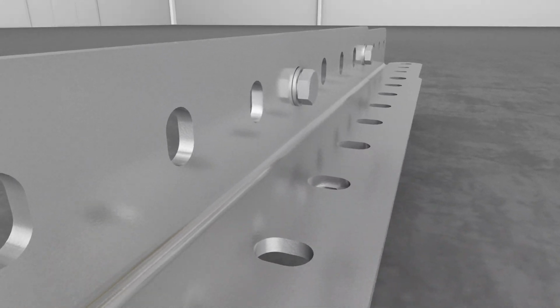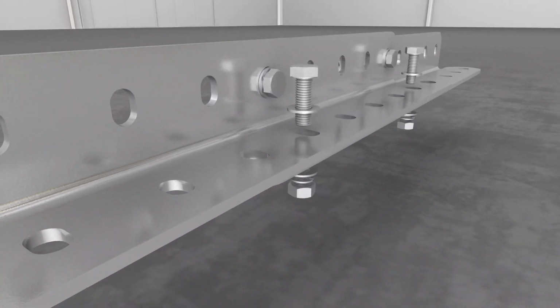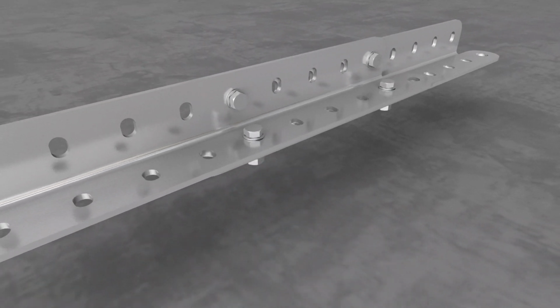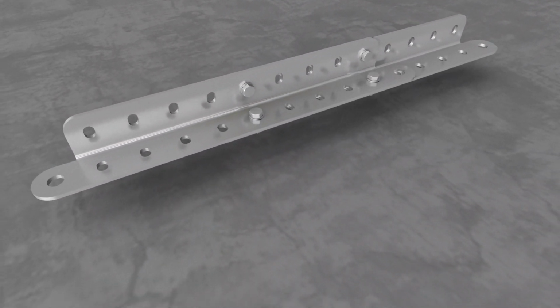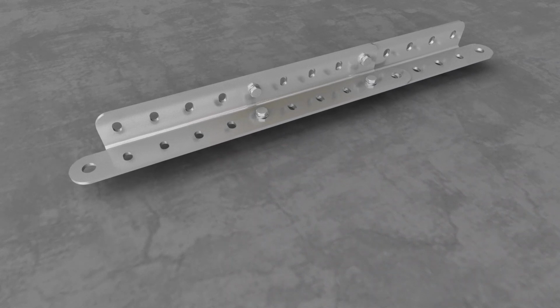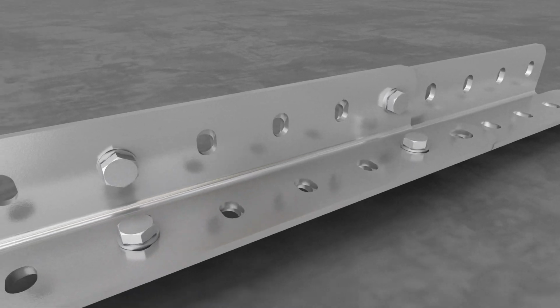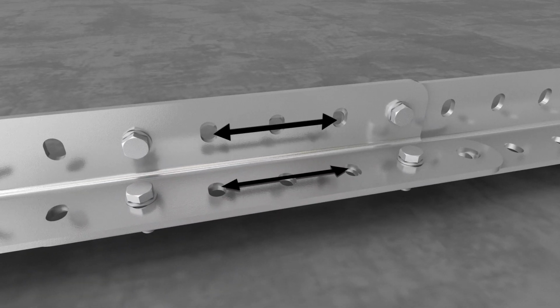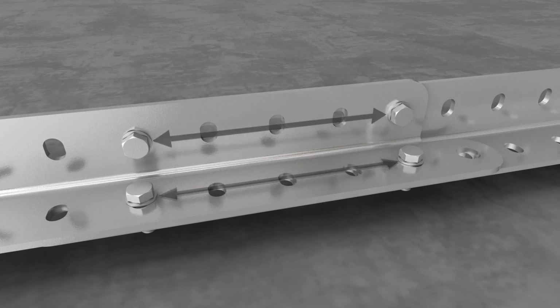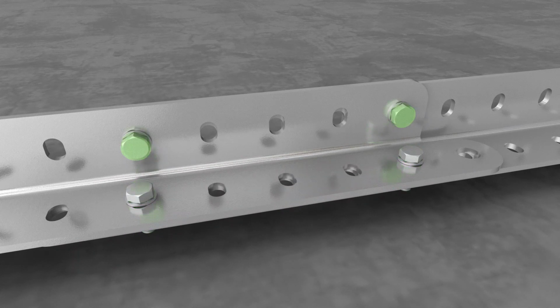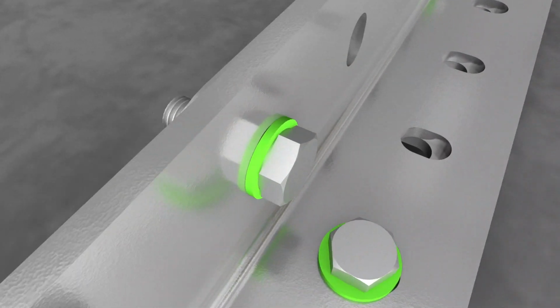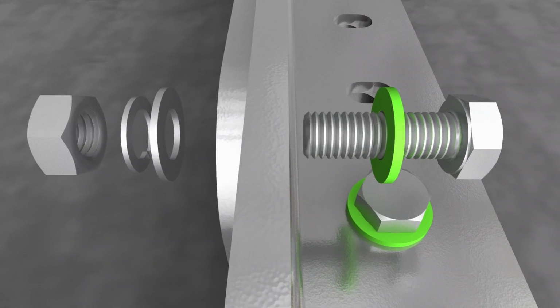Once correctly positioned, insert a minimum of 4 M10 40mm bolts through the hanger link arm assembly with the bolt heads facing inwards. The bolt assemblies must be positioned as far apart as practicable and always with 2 bolt assemblies in each flange. Flat washers must be positioned beneath the bolt head, with additional flat and spring washers added prior to the nut.